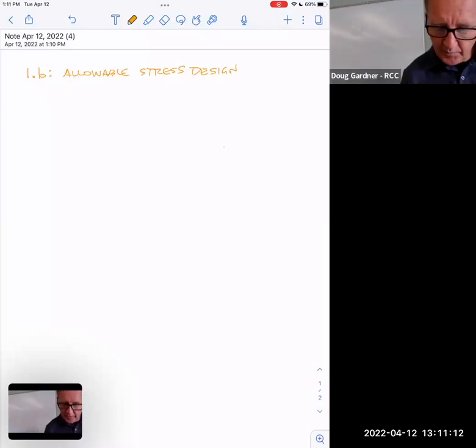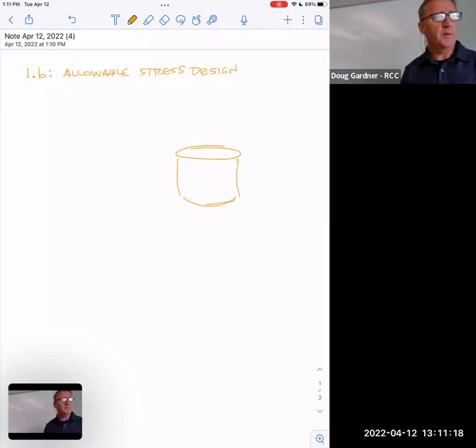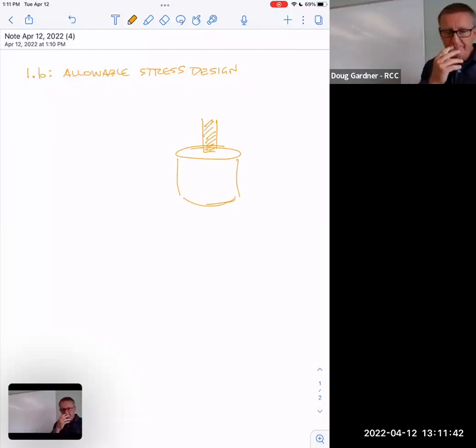In other words, and I have a problem like this in an assignment, but one of the things I do a lot, there's a pier that you pour concrete on all the time. That's called a sonotube. So it's kind of like a toilet paper roll, and you just pour concrete inside it and rip all the cardboard off, and now you got this piece of concrete there, and it interacts with the ground because concrete does really well touching dirt. And then you put your post on the top of it. And so that represents your footing, and now that can hold up your deck or whatever it's doing.